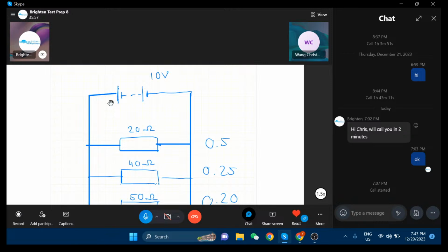So in its simple statement, when you have such a parallel circuit, you always have the same voltage in each one. There may be different elements, more complicated, whatever. But that box here, if you simplify it down of whatever complicated structure you may have in that stream, that box in the end is 10 volt. Same as this one, same as this one.